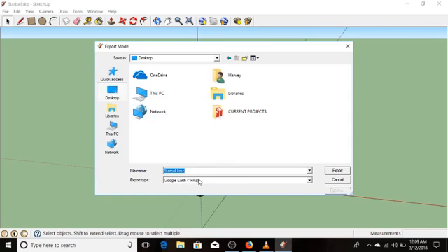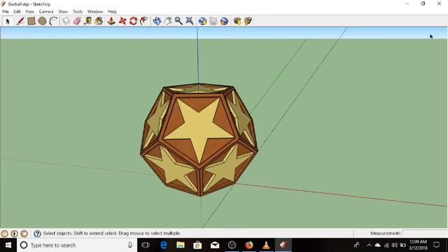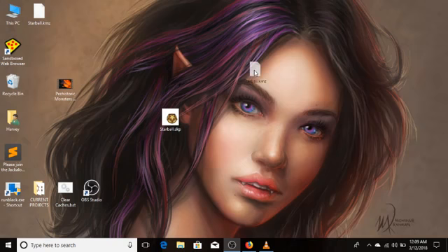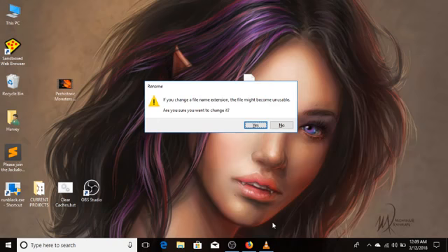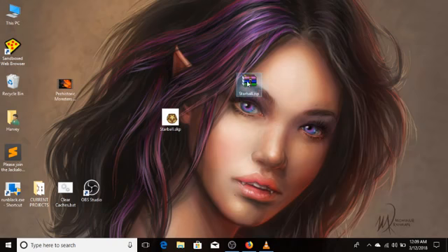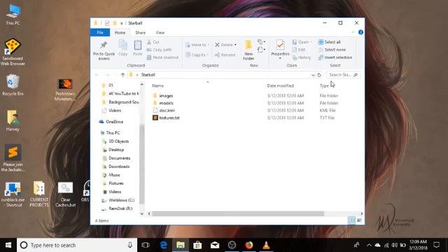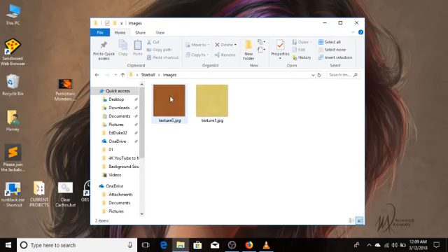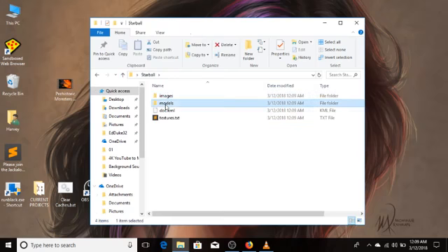A small problem, SketchUp 7 only knows Google Earth format, but that's not really a problem at all. Stick with me for a moment. It's not a problem at all because the KMZ file is a zip. It's a standard zip with a different extension. Back. ZIP. So extract it. And inside here you will find the textures. And inside here you will find a one-piece DAE to be uploaded into World.